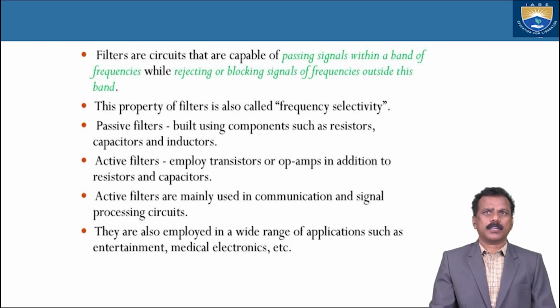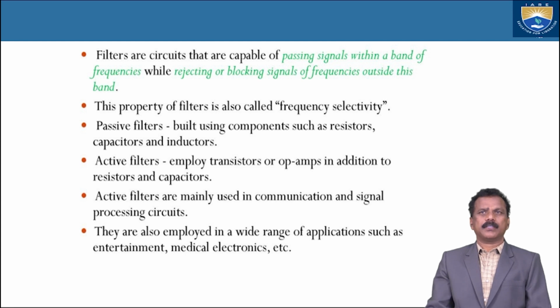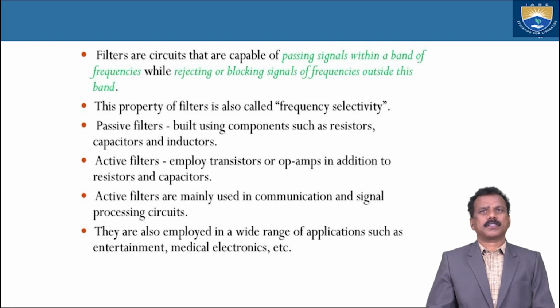Okay, filters are circuits that are capable of passing signals within a band of frequencies while rejecting or blocking signals of frequencies outside this band. This property of filters is also called frequency selectivity. Passive filters are built using components such as resistors, capacitors, and inductors.